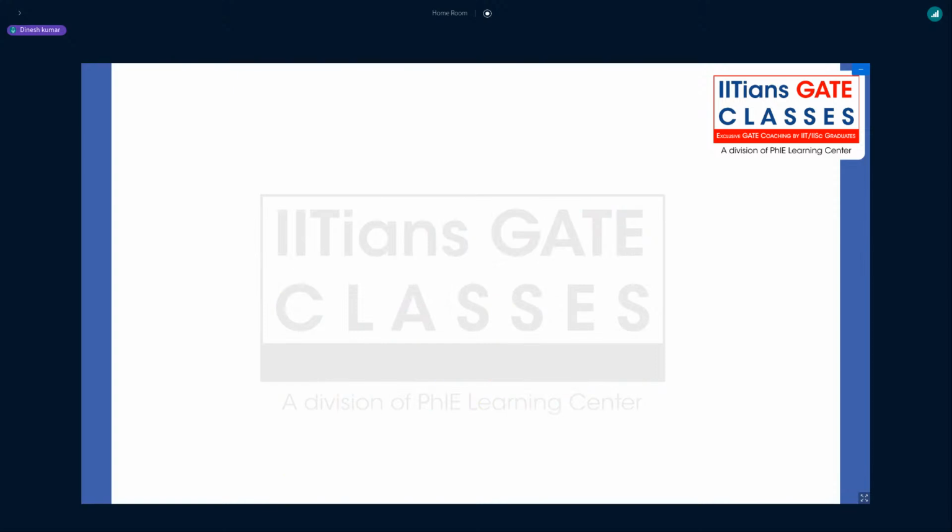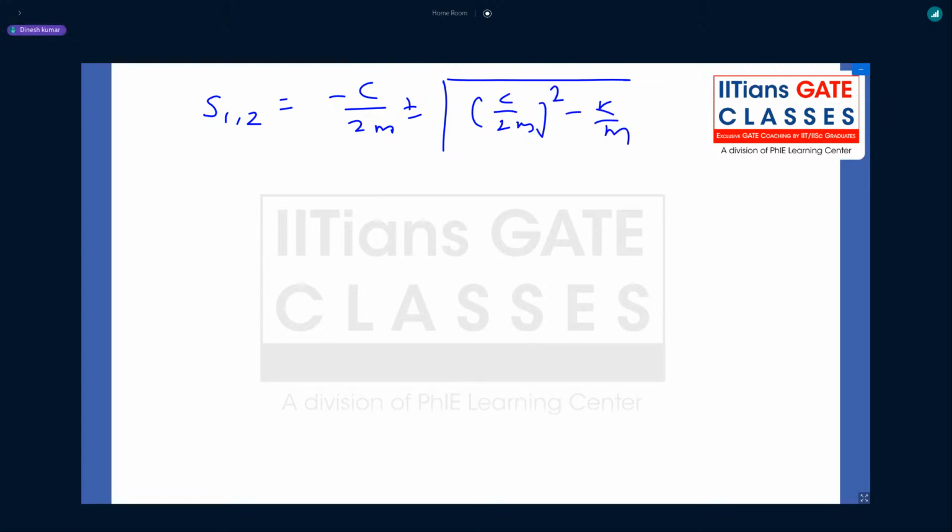So what are those roots given by? S1, 2 will become minus C by 2m plus minus under root (C by 2m) whole square minus K by m.